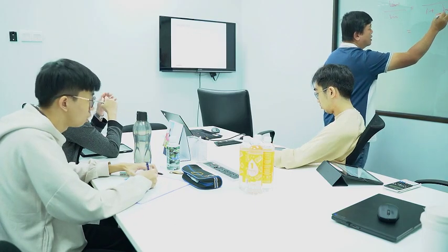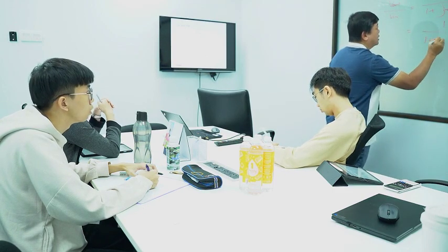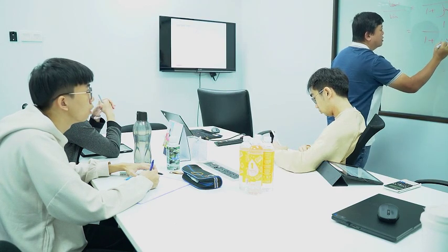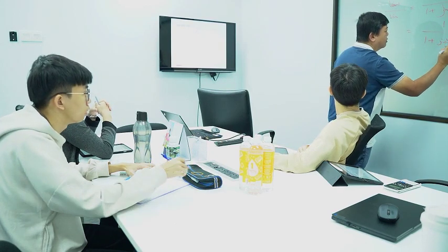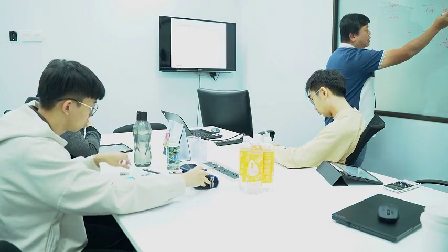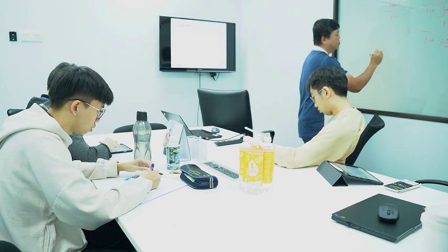This jω refers to your input frequency of a filter. So you change a bit here, become 1 plus jω divided by ω0. ω0 actually is equal to 1 over RC. Actually I try to put ω0 equal to 1 over RC.